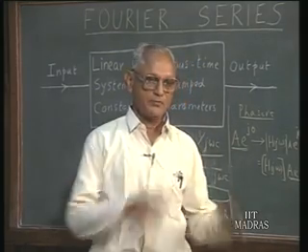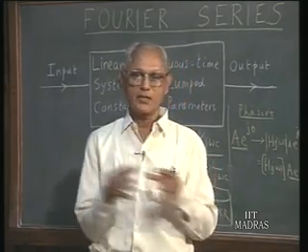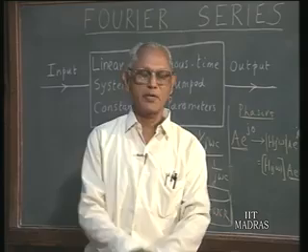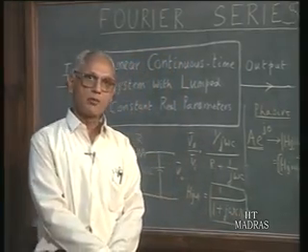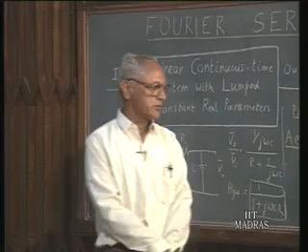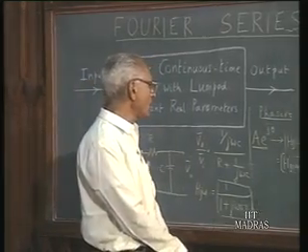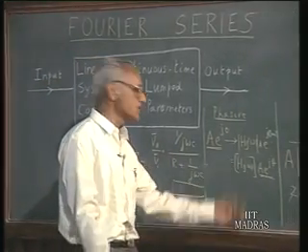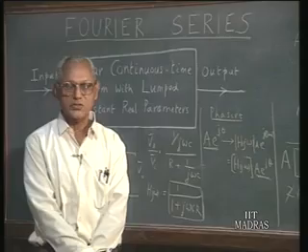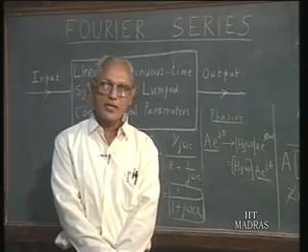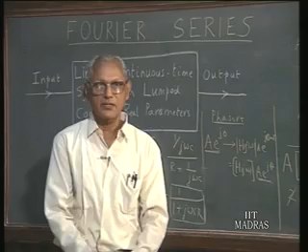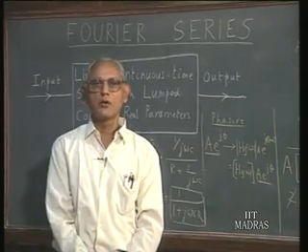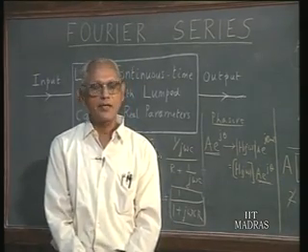You can find out the parameters of the input quantity and the output quantity using your instruments, maybe an oscilloscope, maybe voltmeter, whatever you are having, measure the output phase and output magnitude in relation to the input, and measure the system function H of j omega for different values of omega. This is very convenient for experimentation purposes. Not only sinusoidal functions can be easily generated in the lab, but also the input-output relations can be quite conveniently measured.